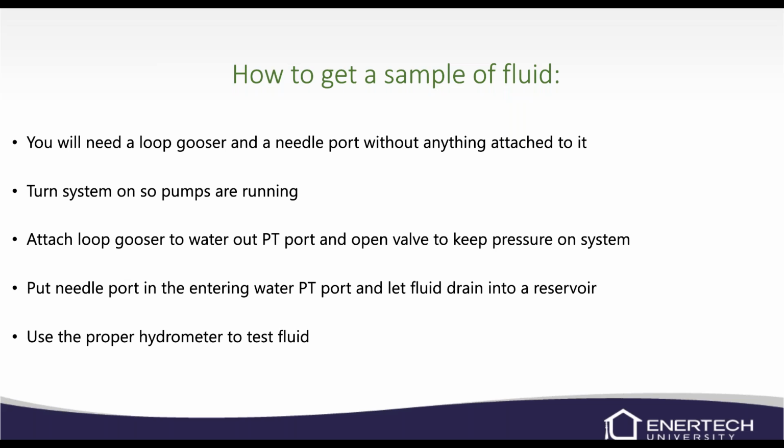If you ever have to send a water sample into Enertech, we can test it. We do have test kits now available, so you can test it in the field. But if for some reason you want us to check it, just make sure that I get about 16 ounces of water. So a little water bottle full will be fine for me.